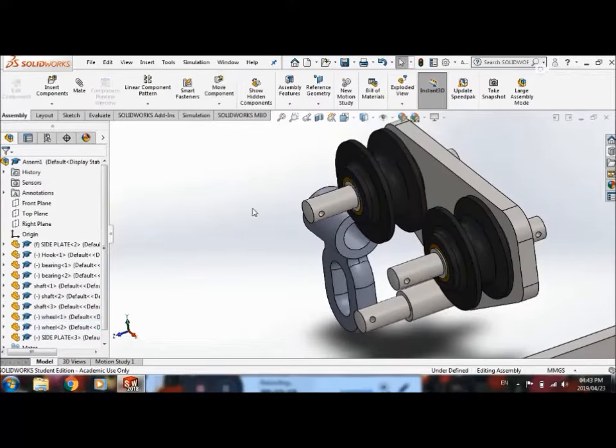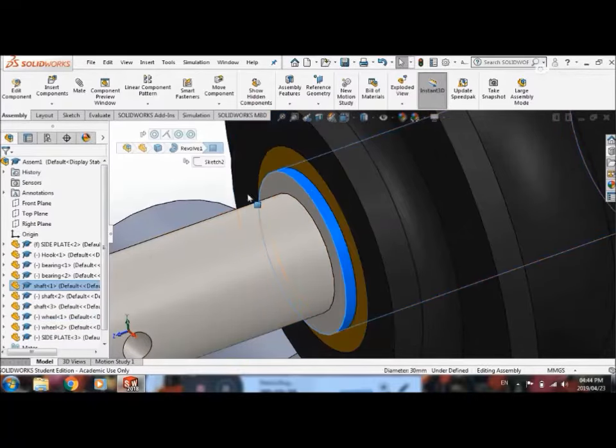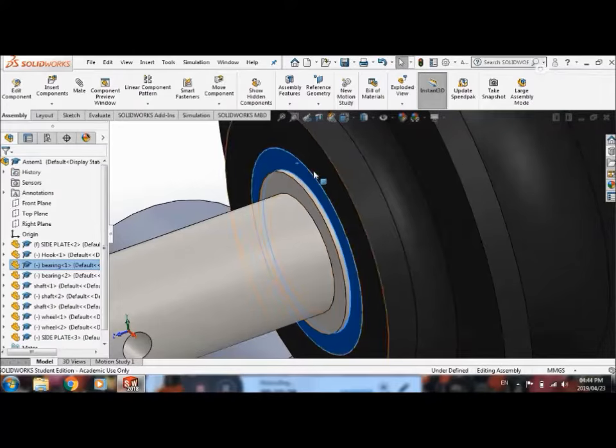I don't know if you remember when we did this assembly in class, we actually said that that cylindrical part has a length of 60 and the bushing had a length of 59. So to be technically correct, we actually need to place it nicely and evenly spaced from each side.